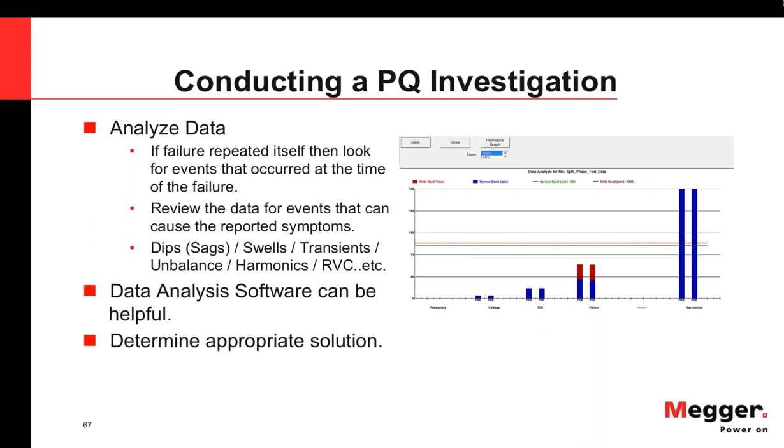How long do I leave the unit there? One of the questions we asked in the beginning was, how often does this problem occur? We want to leave the unit for at least one complete cycle. So if the problem happens every couple of days, the recording should be at least 2 days. If the problem happens only once a week, you want to leave it for at least a full week to try to capture the event that is causing the problem.